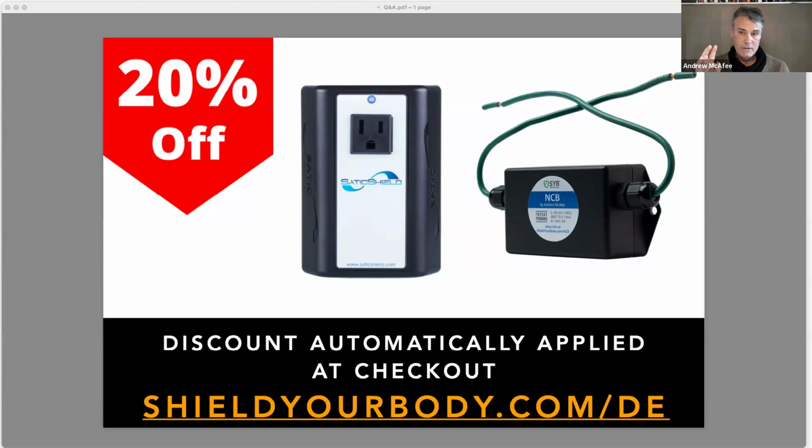Now, the grounding conductor is the real controversial one. There's an electric field around some grounding conductors because it could be carrying current. Whether to cut the grounding conductor as well with a switch, a 3-pole motor switch, is very controversial, but sometimes it's absolutely necessary. You have to measure what's the resulting electric field with all 3 conductors cut versus just cutting the hot and the neutral.